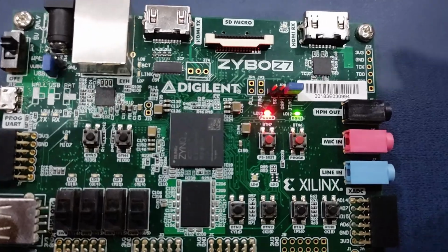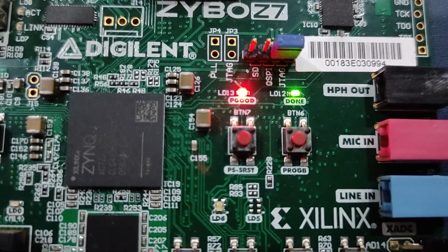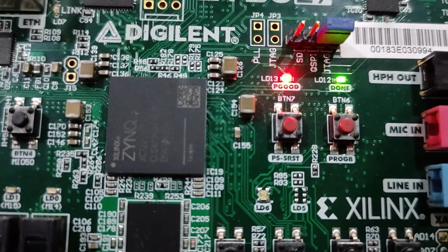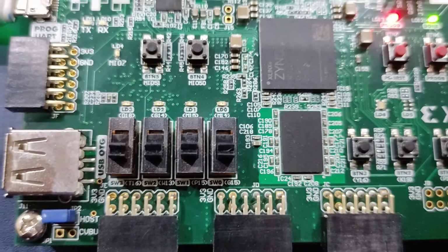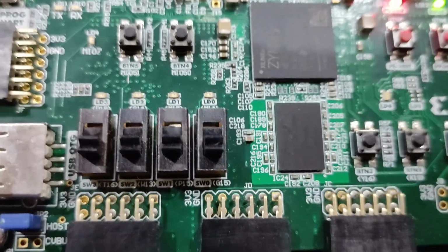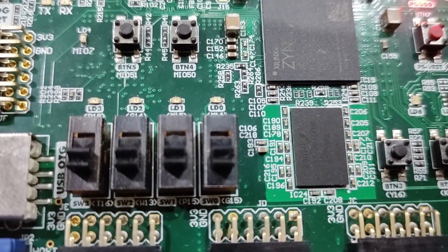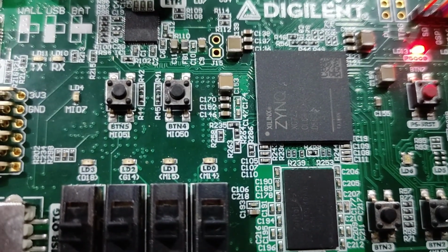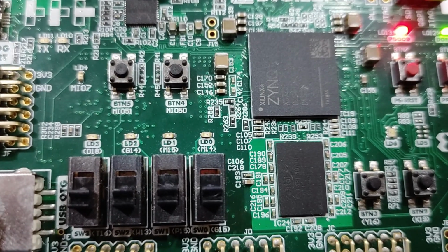So this is our FPGA, and we can see it is successfully programmed because this green LED is high, which is the done bit. This LED goes high when the FPGA is programmed, and it tells us that the FPGA is powered on. Here we have 4 input switches and 4 output LEDs. We selected the inputs W13, P15 and G15 as A, B and carry in, and the outputs M15 as sum and M14 as carry. At this time all the inputs are 0, and the sum and carry are also 0.